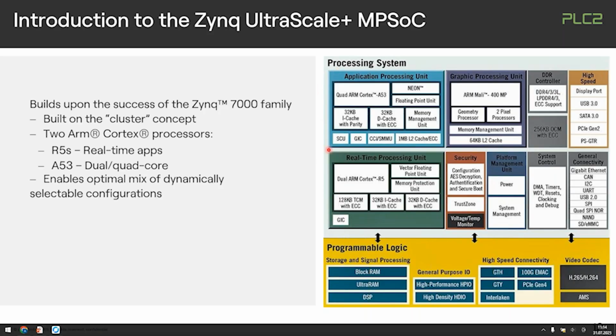These clusters of CPUs are there in these adaptive SoCs to take on different tasks already within the CPU system. So you have additionally co-processing elements like the GPUs. The GPUs may be differently available in different devices, so you have to be careful about your requirements, because they scale the kind of device family that you can use. There are even now GPUs on the horizon with the Versal AI Edge series Gen 2, which has GPUs yet again, where the Versal Gen 1 devices didn't have. So this is really what you have to look into when you deal with these device sources.